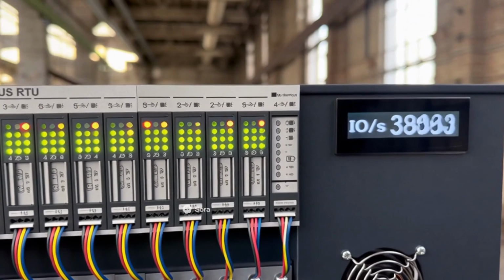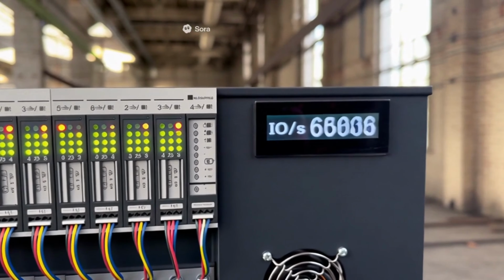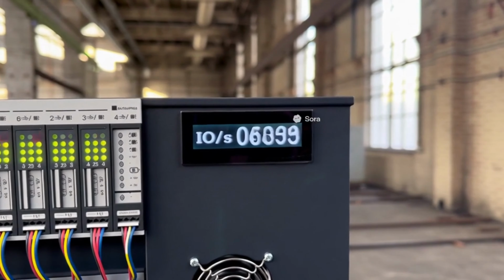This one just depends on what you're doing, but in most cases, it's not true. Modbus was never meant to transfer gigabytes of data like video or high-frequency analytics. It was built for industrial control, where precision and reliability matter more than raw speed. Typical Modbus RTU networks can transmit data fast enough for thousands of I/O operations per second, and Modbus TCP takes that even further with Ethernet-level speeds and parallel device access. For most automation systems, whether you're monitoring temperature, current flow, or machine states, that's more than enough bandwidth.